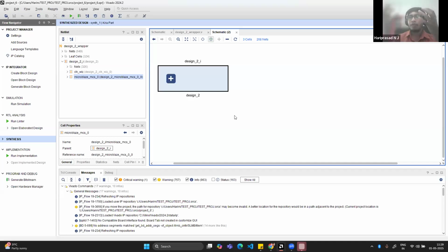Let's say you designed one counter, you don't connect it to any IO, and you just put it into the FPGA and run. It is not going to synthesize. It will trim off and show zero resource. It will not run, because it always expects a closed circuit. We are building circuitry. Let's say I'm using one lookup table with no input and no output. Even if I map that configuration bit, it is of no use, no meaning. Only valid, meaningful signals will be mapped into the FPGA.